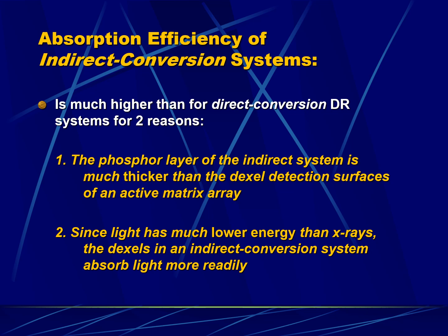Oh yeah, okay, because it's not the same system as an indirect. An indirect actually uses a polarized electrode at the top to pull the electrons up away from the capacitor. The amorphous selenium does not use a polarizing electrode, okay, and so the electrons have to drift. And if the amorphous selenium layer is too thick, they'll just reabsorb.